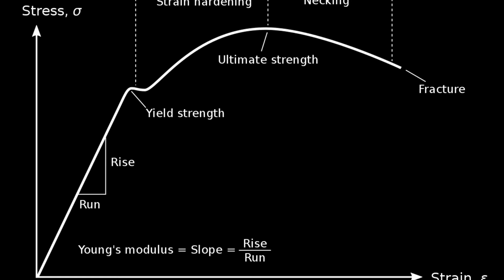Also something worth noting, if you don't have Simulation Pro in SolidWorks, anything past this linear line, so anything past the yield strength, is not going to yield the correct result, because anything that isn't Simulation Pro can only do linear simulation. So you're going to get fake values that are way higher for the stress that your part can take. So don't trust any of the values above the yield strength, because that's not going to be correct.